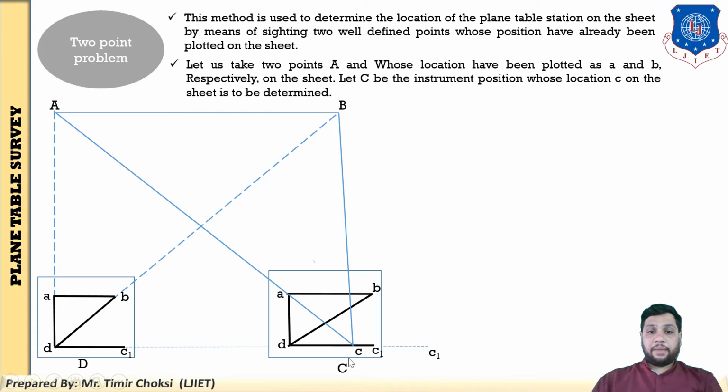Okay, I will repeat this step. Here you have the C point obtained from A. Now you keep the LE touching at C, and when you draw the rays from C, your projection will be right as well as your orientation will be right. So your C line will intersect small b, but here it is not intersecting small b. So a little bit of error is there. So how to solve the error and get a better position for taking the C station? Now I will explain. Okay.